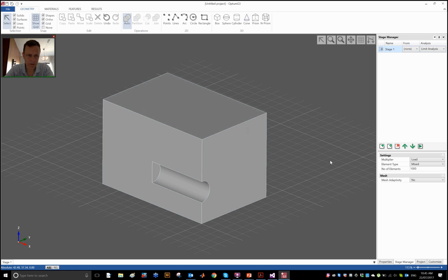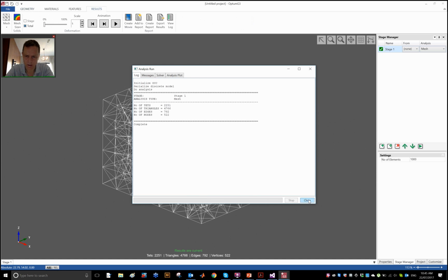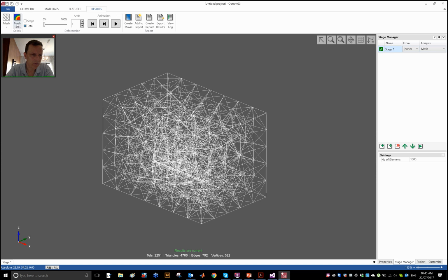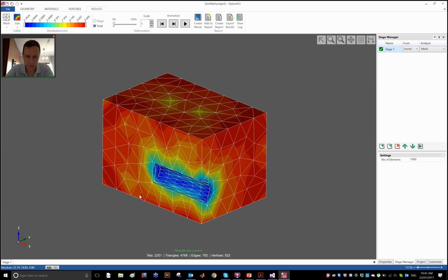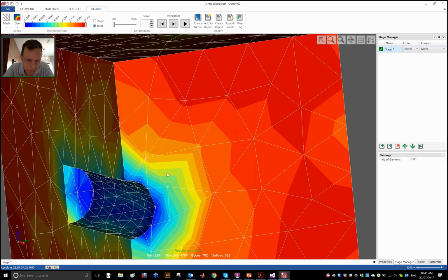But before I actually start applying material and boundary conditions and so forth, I want to just have a look at the mesh that I get, because it's always a bit dicey how, especially the base of these cylinders will be discretized, also the rest of the cylinders, because there will be an approximation, of course, and it's just a good idea to have a look at that. It is not too critical in this case, but we want a fairly nice approximation of this circular tunnel.